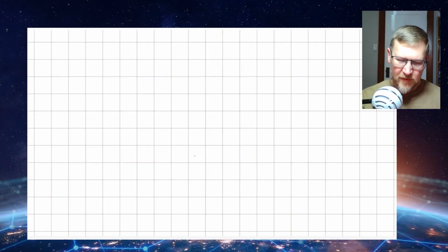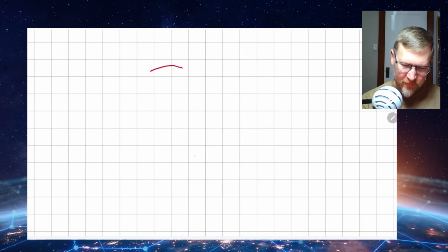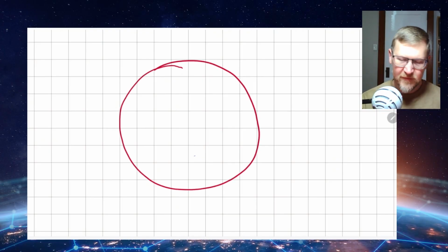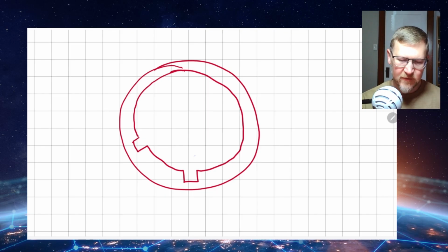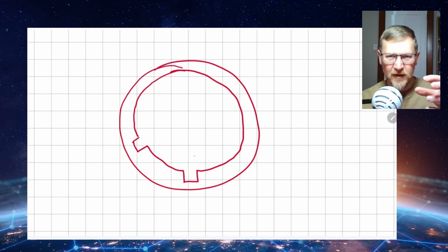Well, the simplest answer is to make it impossible for someone to put the connector in the wrong location. This is a technique we call keying. So I'm going to go to the tablet here, and we're going to show you what the keying might look like. If this is the circular connector that we're so often seeing in the aerospace industry, and you can do this on other types of connectors as well, they often provide some sort of tab features, something that sticks out on the connector or on the receptacle side. Usually it's a depression. So you have these interfacing features.